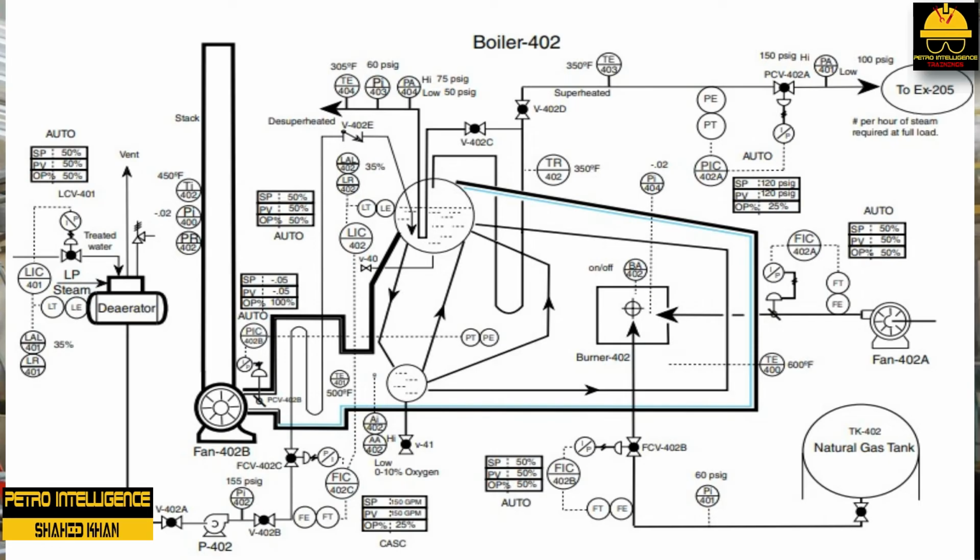During the desuperheating process, part of the superheated steam is routed through the boiling liquid in the steam drum, cooling it down to a lower pressure. The boiling water is cooler than the 120 psig steam and reduces the pressure to around 60 psig.